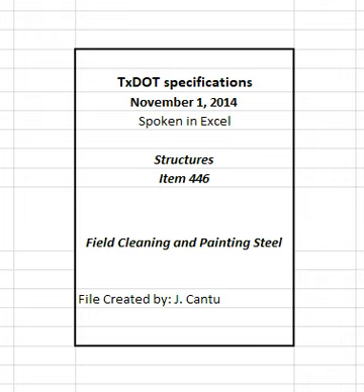4.7.2 Containment. Submit a plan that details the procedures and type and size of equipment proposed to keep public property, private property, and the environment from being adversely affected by the cleaning and painting operations. Approval of the plan is required before cleaning and painting operations begin. Containment is not required for painting newly erected, shop-primed steel other than to comply with Section 446.4.6, cleaning and painting new steel.